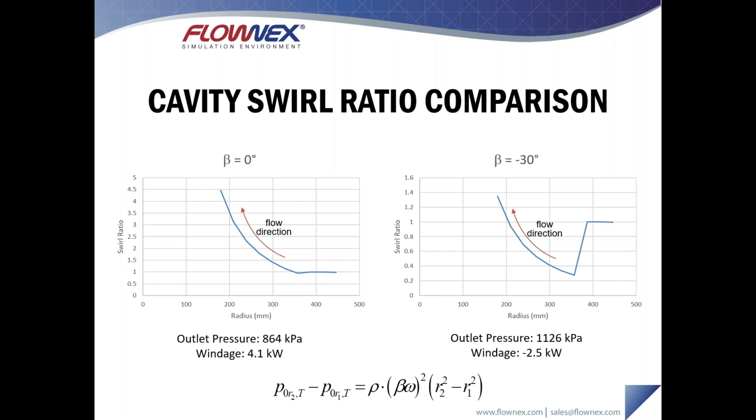essentially the same tangential velocity at the end of the cavity, but in reality, that higher velocity results in a higher pressure drop in the compressor tapping holes, the radial inward holes, and the pressure drop increases with the square of the velocity, whereas the length increase from changing the degree to which we backsweep the holes only increases with a linear relationship. So the length of the channel increases the pressure drop linearly, while the velocity in the channel increases the pressure drop by an exponent of 2.